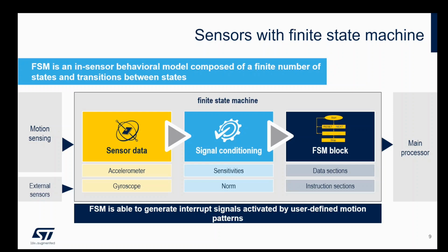Next is that you get out of your car and you start to walk. So the accelerometer can detect that you got out of your car and you have started to walk. So those are two other states. A finite state machine can do this for you. So the finite state machine can then tell you, okay, this is where you parked your car. So a higher level application can then use this information and bring you back to where your car is in a parking garage in a shopping mall. So that's how a finite state machine can be used to traverse between different states.